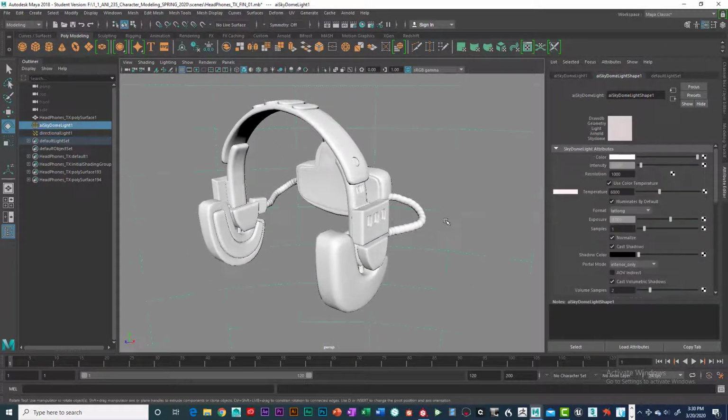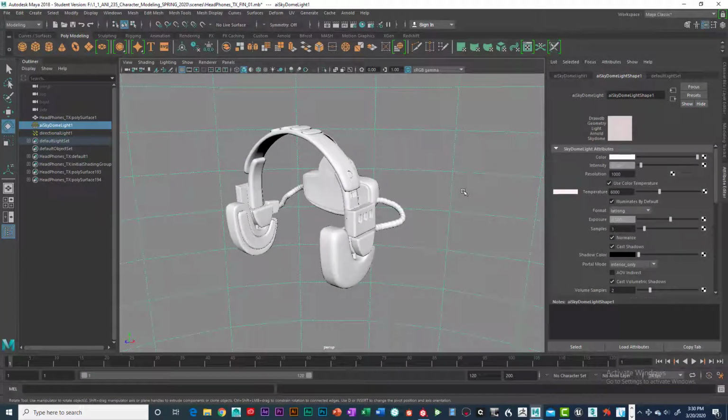Now, one of the things I do want to mention is that your metallic surfaces won't really look metallic unless you have an HDRI image. So go to HDR Haven. That's called the HDR Haven, and pick out a really cool HDR image and place it on there. I'm going to pause this and get one really quick so you can kind of see what's happening. Okay, I'm back. I went ahead and got Delta, if you guys are interested in HDR Haven. It is Heaven, but we just call it Haven.